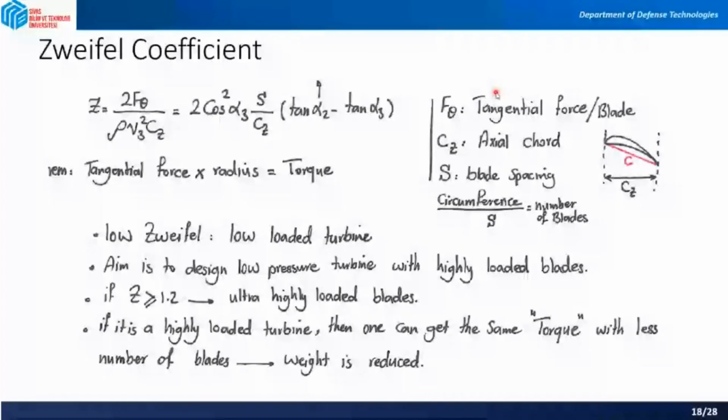The total pressure is 1.4 megapascal. Mass flow rate is 40 kilograms per second. And the mean radius data is given to you. What is the mean radius data in here? You have the Mach number at the entrance. You have Mach number after passing the nozzle guide vane, so it is still supersonic. Your peripheral velocity is 400 meters per second.